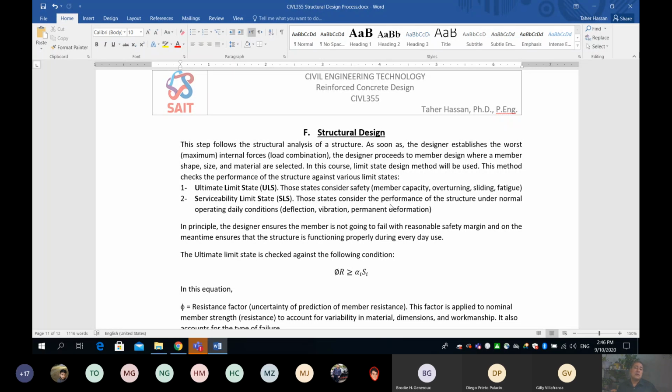What else? Okay, probably for the tiles. Guys, we have plenty of marks in this course, so for the sake of time, I'm gonna answer. Flooring comes on top of the floor. If you have lots of deflection, flooring will crack. How about partition walls? They go on top and you will see cracks. And by the way, this happens and the owners will just sue the structural engineer because of the deflection.